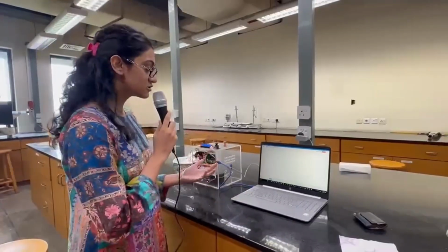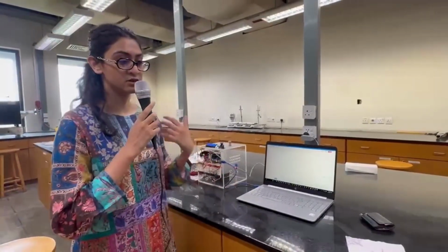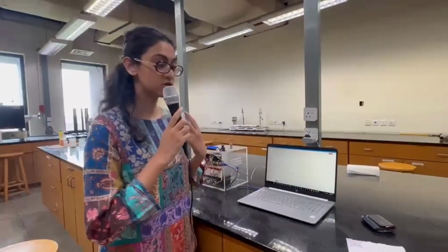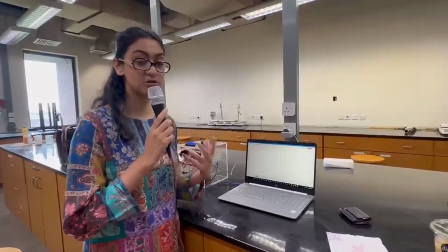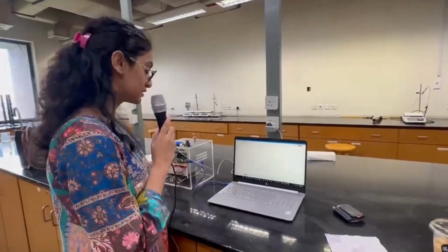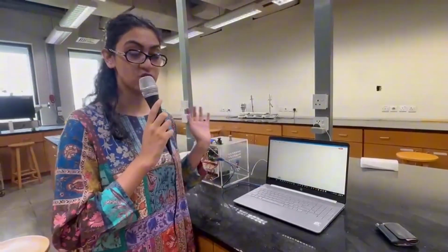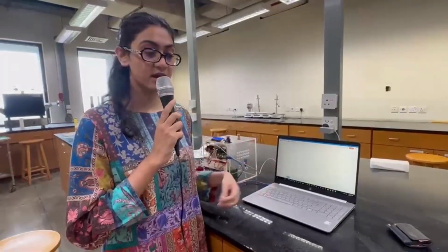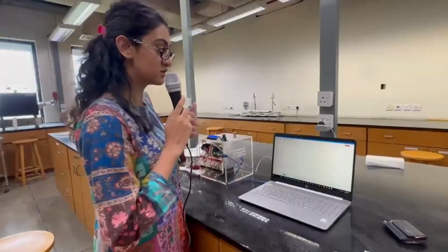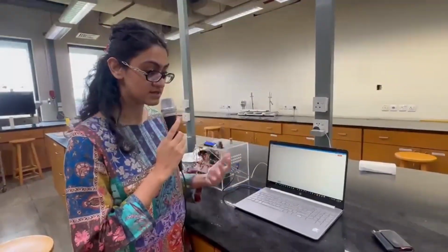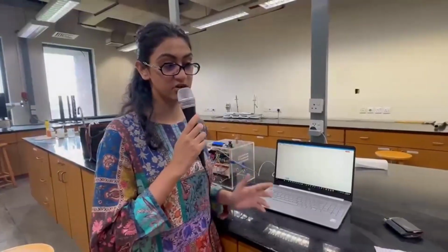The proportional control looks at this error and gives you a control output proportional to that error. The integral control then comes in, and what it does is it logs all of the error from the past and gives you a cumulative result from that error to minimize any sort of fluctuations and to get rid of a steady state error that you would have gotten with the proportional control.